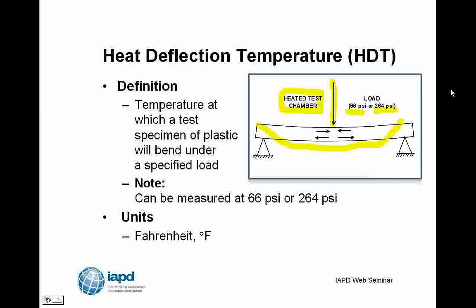Now, I want to throw in a big word of caution about heat deflection temperature. The temperature at which you can successfully use a plastic material has a lot of complexity to it. Many things come into play. Dynamic modulus, as Larry DeSanto from Ensinger discussed. Thermal stability, how long it will take for the plastic to get brittle. Creep characteristics, will the plastic move around over long periods of time?